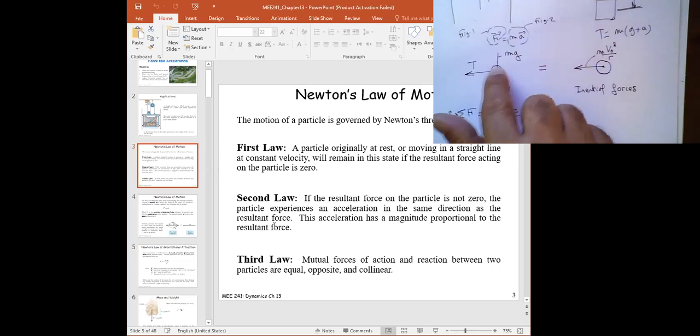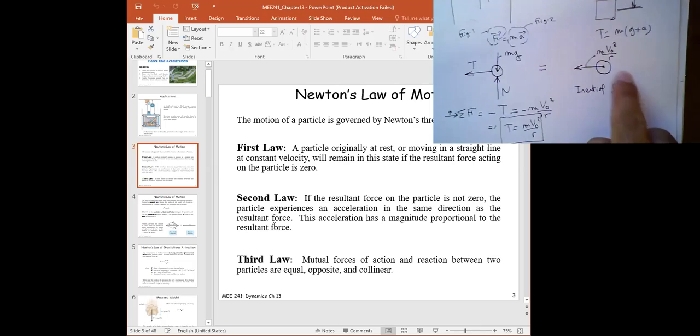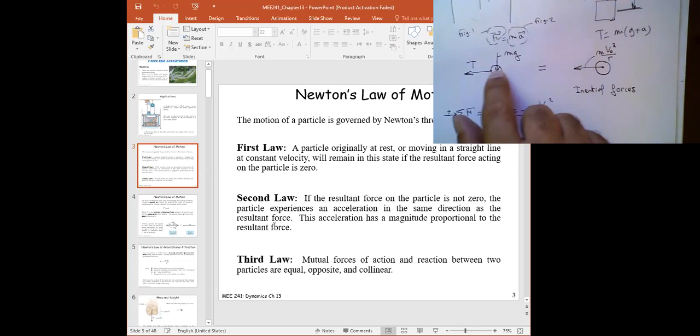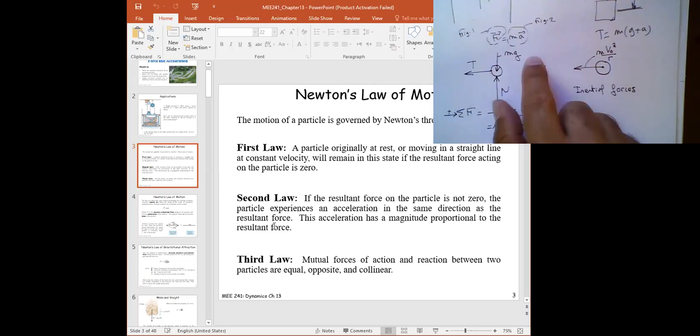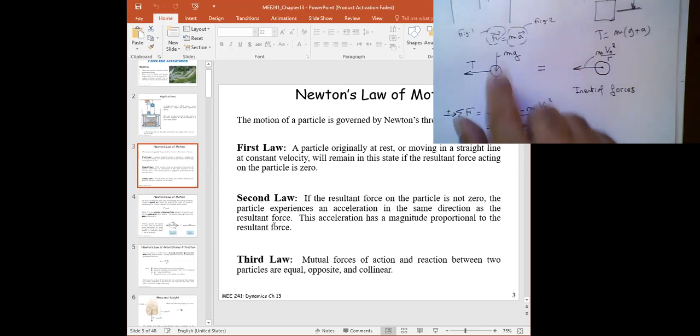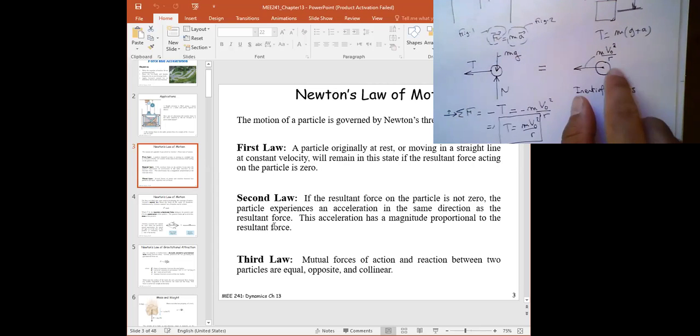Okay, in one figure we put the external forces, and on the other figure we're going to put the inertial forces. It means whatever accelerations you have, you multiply them by the mass. Notice that the reason why we call them inertial forces is because these forces are applied at the center of gravity of the object. Just like what you have with mg, because mg is kind of a form of acceleration, but we're treating it as a force, so we'll just do m times a, but we always have to put that at the center of gravity of the object.